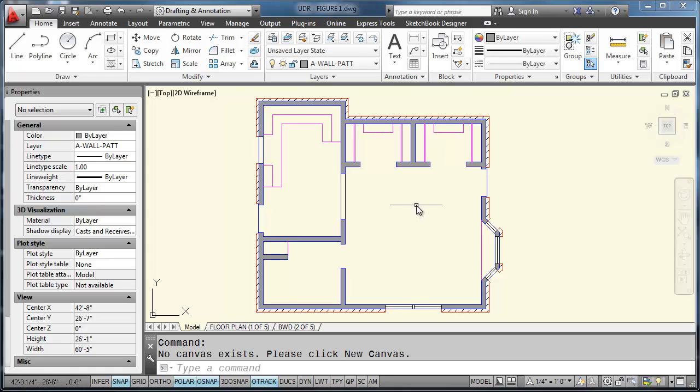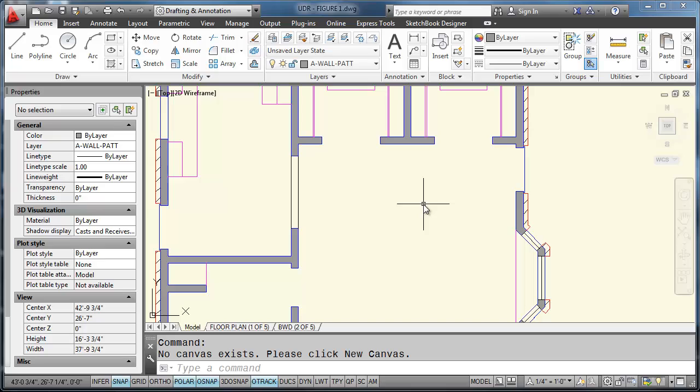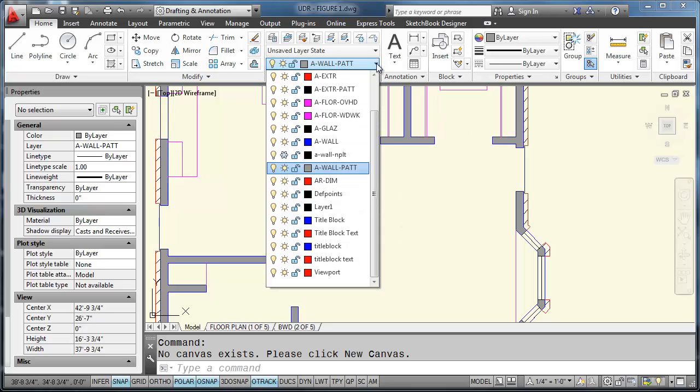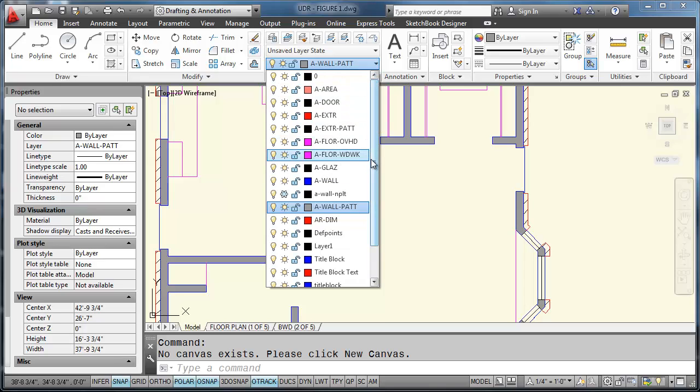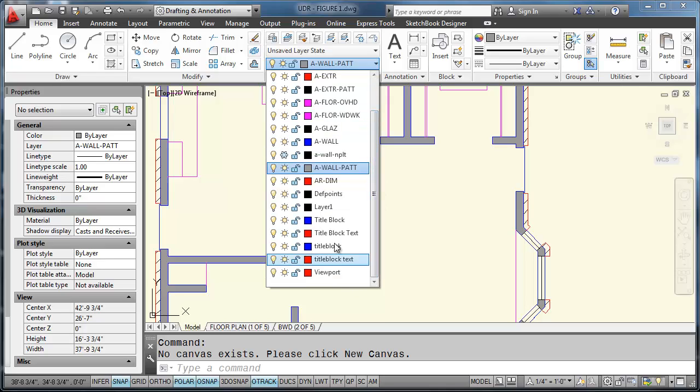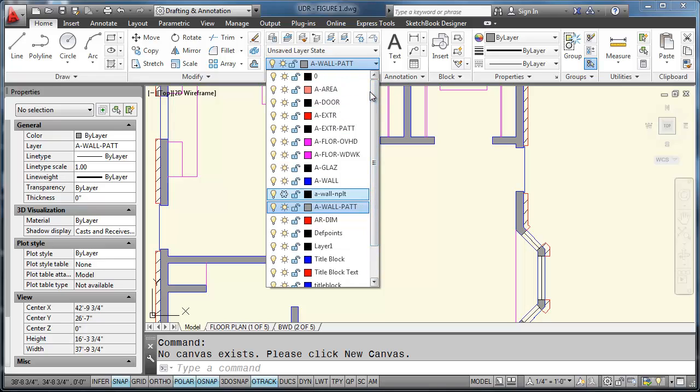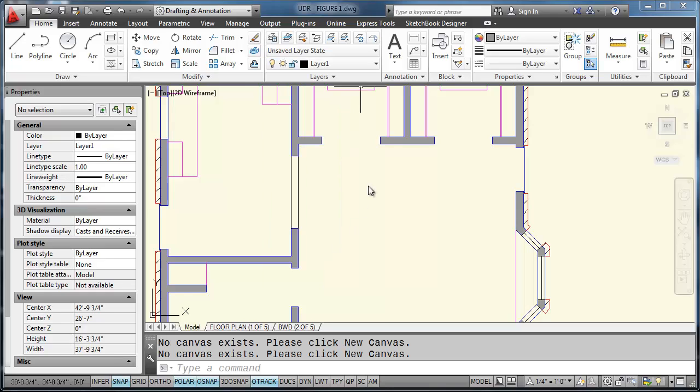We have two sizes of text. We have small notes and room names. The room names are 3/16 of an inch, and the smaller text is 3/32. So let me set my layer for my text. So we'll set up our text layer, which I can't seem to find. So we'll place it for now on layer 1, but there should be a text layer for your drawing.